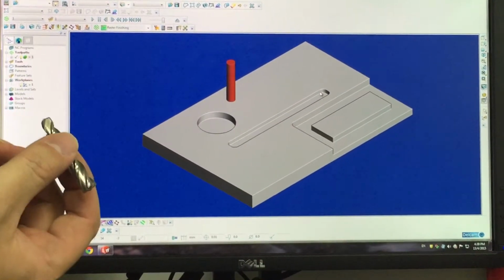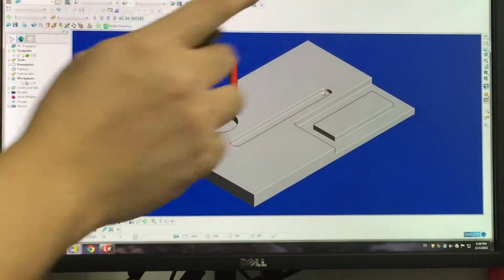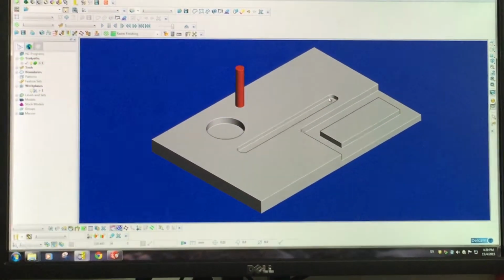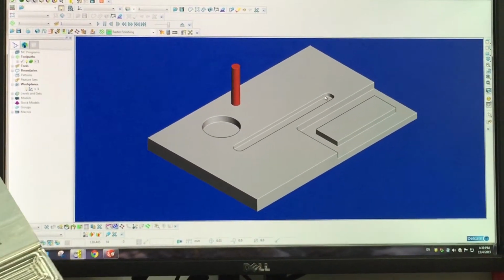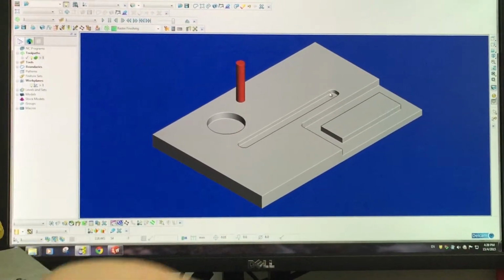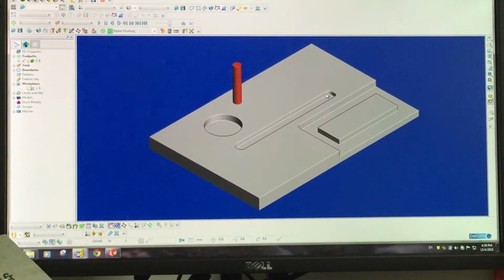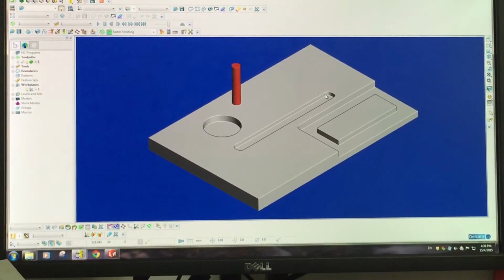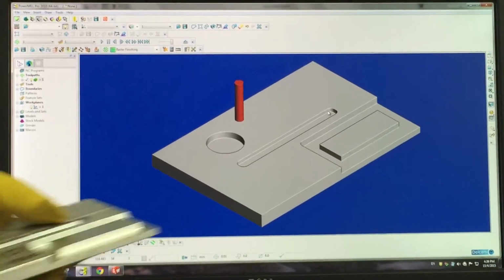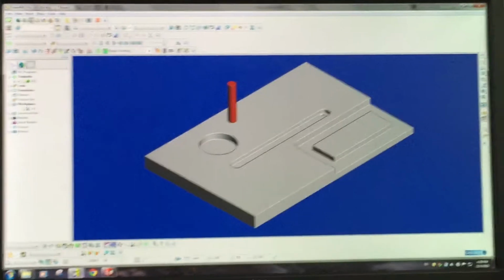If you reduce the diameter, you can only reduce the radius, but there'll still be an arc. Sharp corners are only feasible if you do a milling cut around. So in your drawing later for your practical, still draw a square slot if there is, and when it comes up, it's normal if it's rounded.